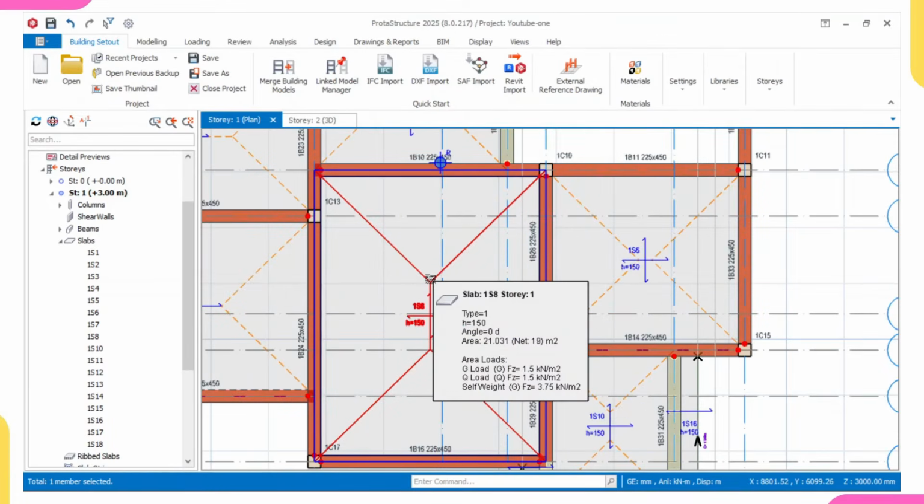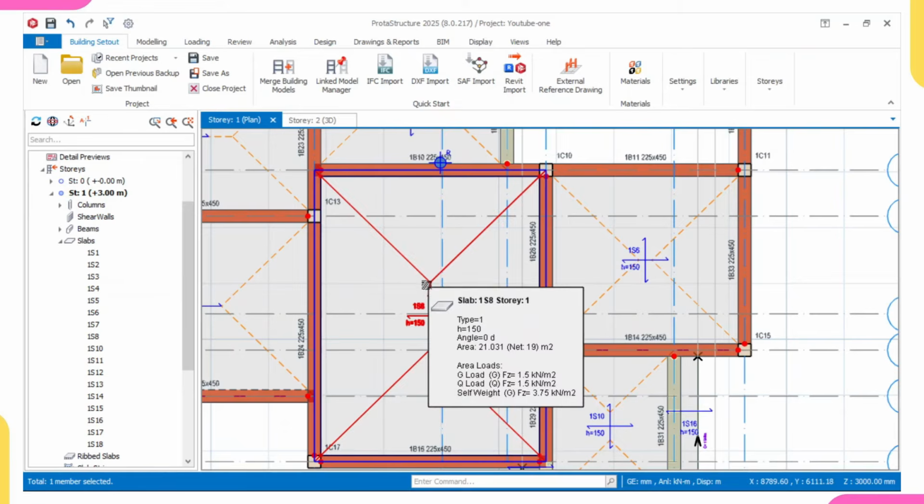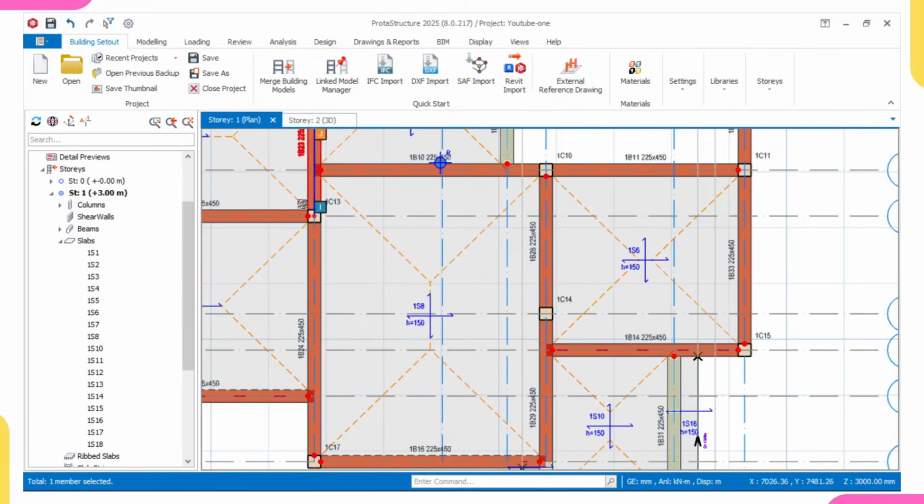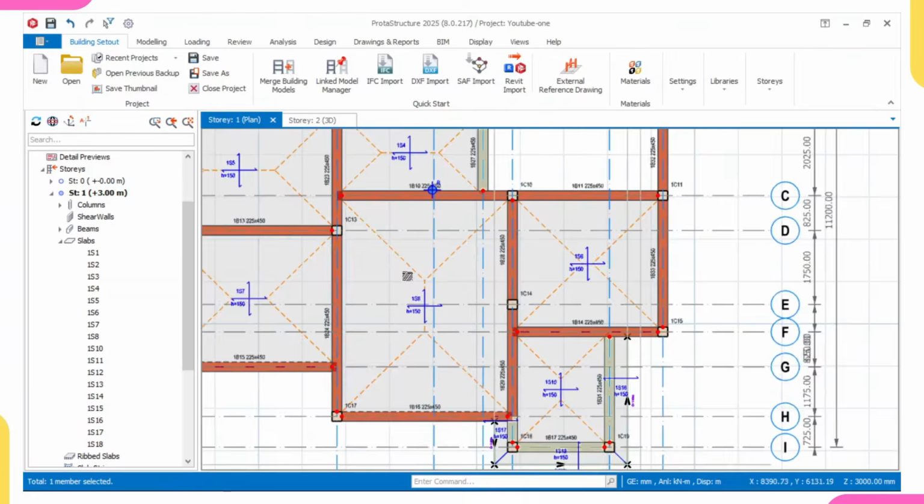See, I mistakenly inputted, and assuming I went on to do analysis, you see that all these beams will be failing because load from two slabs is coming to them. Load from slab 8 and slab 9 will be coming to them because these two slabs are applied on this. So this is the reason why you should do your building model check.